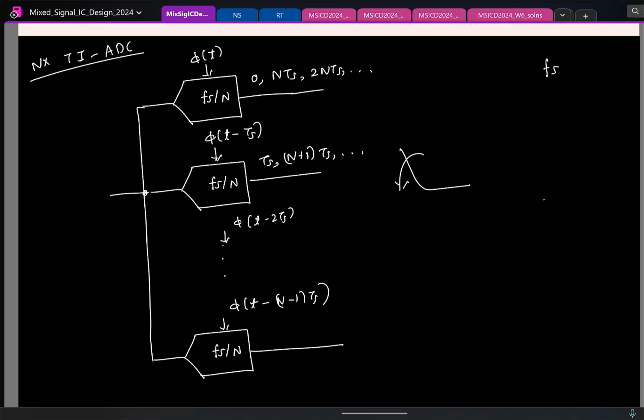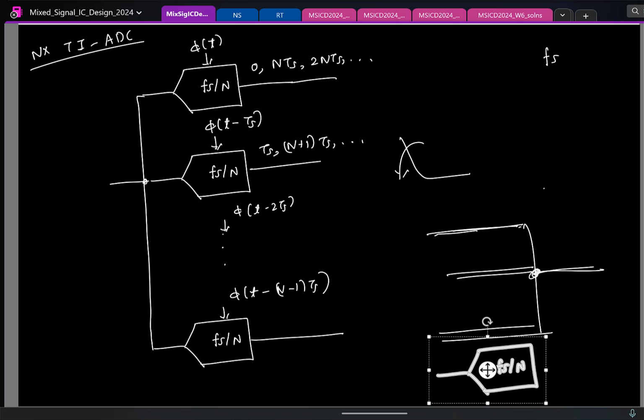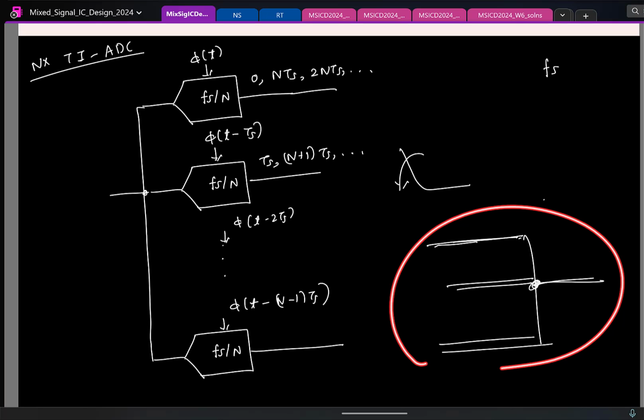If you short it, that is not correct. Basically, if you short them, this node is driven by all of them at different times. Yes, you understand it correctly, but this is not the electrically right way to model this. That is multiplexing.